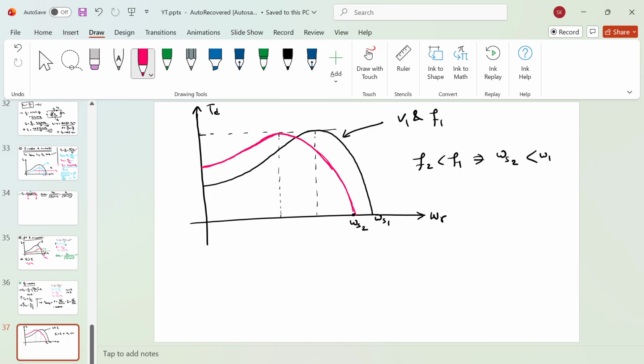So this particular VVVF, variable voltage variable frequency drive, is required for squirrel cage induction motor, where you cannot put additional extra resistance to increase the starting torque. Rather, you can use this V by F ratio constant technique to get more starting torque. So it will be very much beneficial for us.